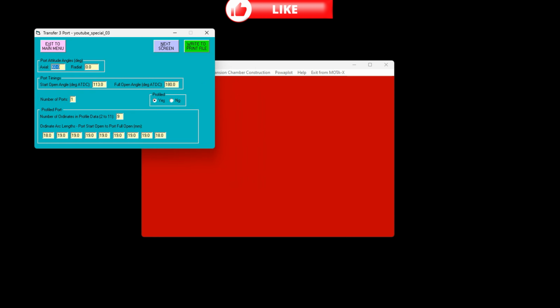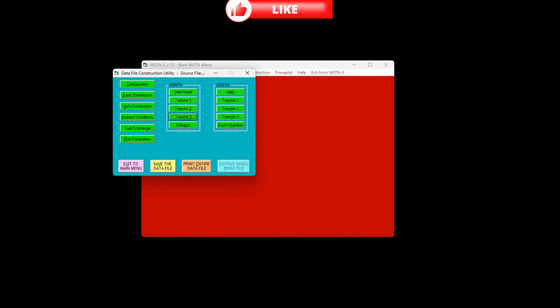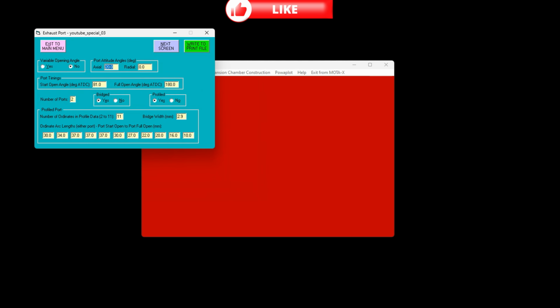This is the boost port, C transfer, only one, and 60 degrees upwards. Maybe some might be quite steep, but I will not change because I have simulated with these values earlier. If you're changing anything now, there won't be equal results.